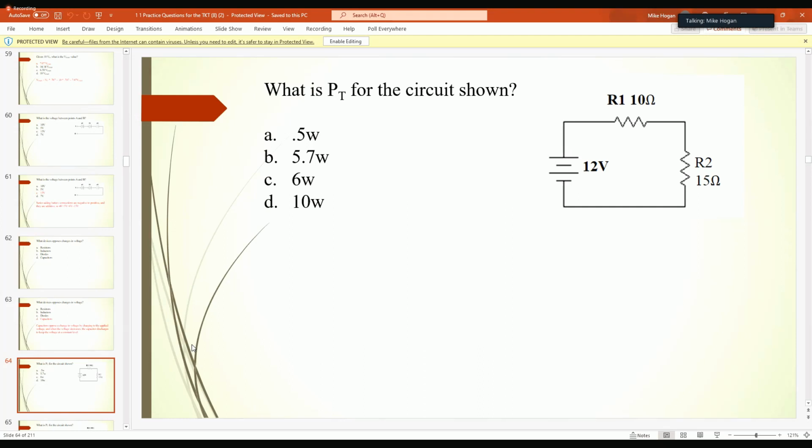You know, there's two ways. We talked about that power formula that was more difficult to remember, that just had voltage and resistance. You could use that if you remembered it. Voltage squared divided by R. However, you don't have to use that. You can always go back to the power formula. Power is equal to current times voltage, and use Ohm's law, right?